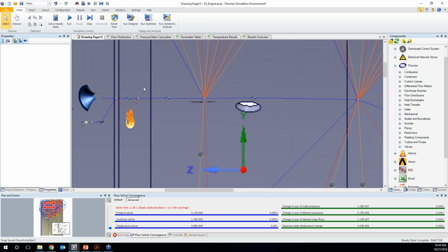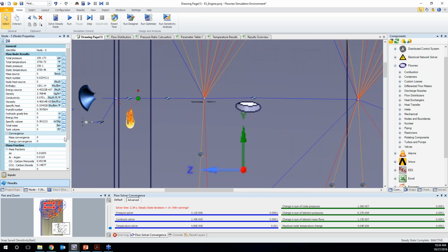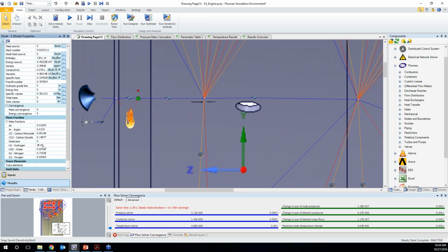All it really does here is just calculate the resulting gases from the combustion process. So what you typically need to do is specify your fuel and your air, and what you also need to include in the fluid configuration definition is all the off gases that you would expect in there, right?